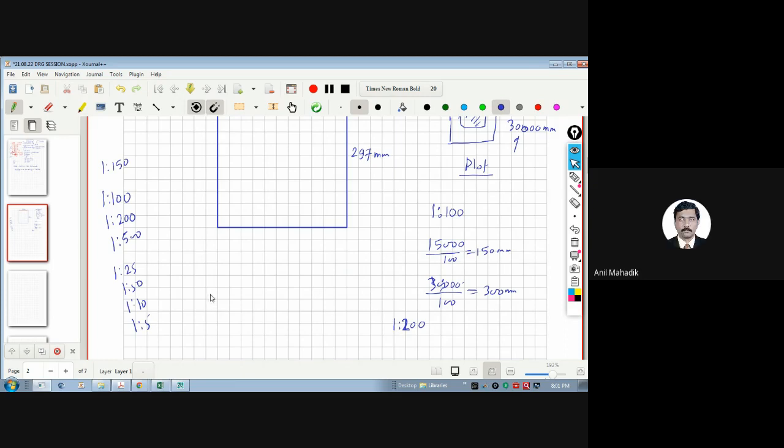Or there are some triangular scales available in the market. All of you may be knowing these triangular scales. This is the cross section of the scale, so you have a different scale on each face, almost 6 scales. Have you used any triangular scales? The scale we normally have is a 1 feet, 300 mm scale. Instead of that we have a triangular scale with markings on it. This marking is for 1:100 scale, this marking is 1:50 scale, like that.